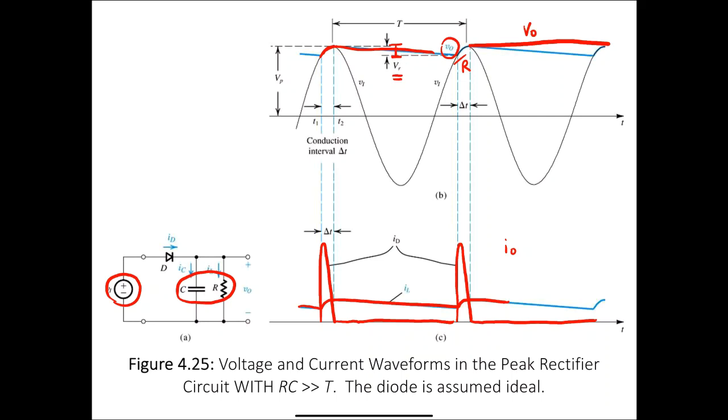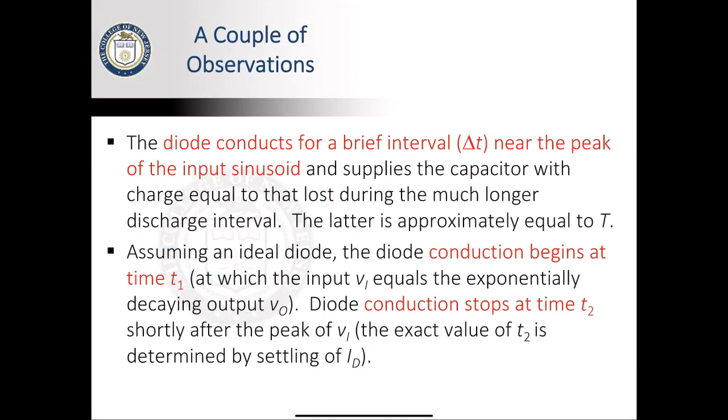So part of this design problem is going to be properly sizing the capacitor and the load such that we have an acceptable ripple, one that is small enough that it still allows proper charging or whatever application it's being applied to, but one that's also practical in terms of what capacitor sizes we have available and how much money we're willing to spend, or resources we're willing to use.